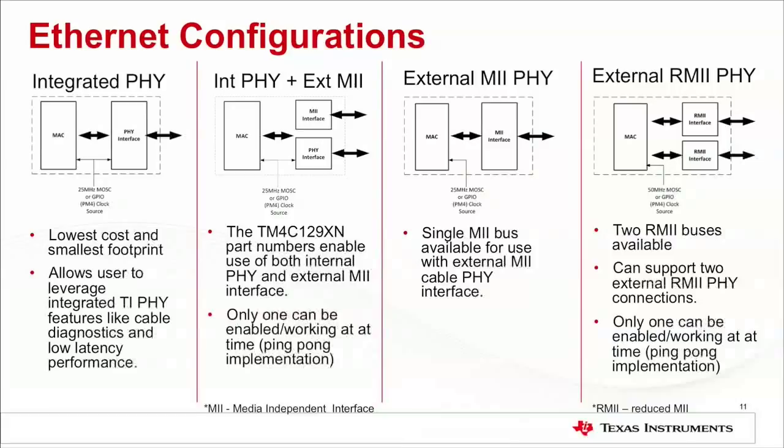The TM4C129X family of microcontrollers provide Ethernet functionality for connected applications in 4 different configurations. This allows you to pick the parts that match your application requirement, package footprint, and cost point. To keep things simple, you can choose a part with integrated MAC and PHY. All you need then is some termination resistors, filtering capacitors, magnetics, and a RJ45 connector.